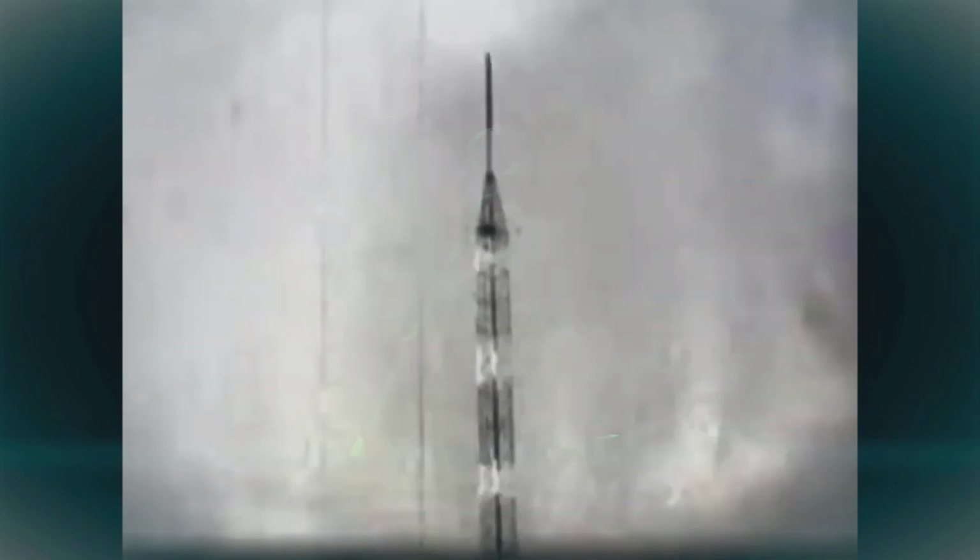A half-wave antenna should measure half the wavelength of the frequency employed. This broadcast antenna measures approximately 309 feet. It operates on a frequency of 1590 kilocycles, corresponding to a wavelength of about 618 feet, or twice the length of the antenna. As radio frequencies decrease, wavelengths increase, and the length of the antenna must increase. So that some radio frequencies would require a half-wave antenna too big to be practical.